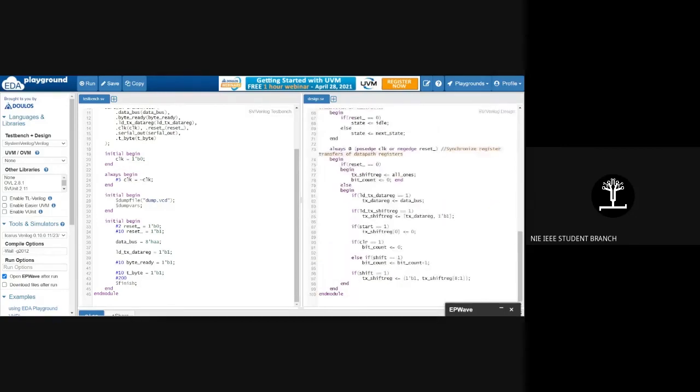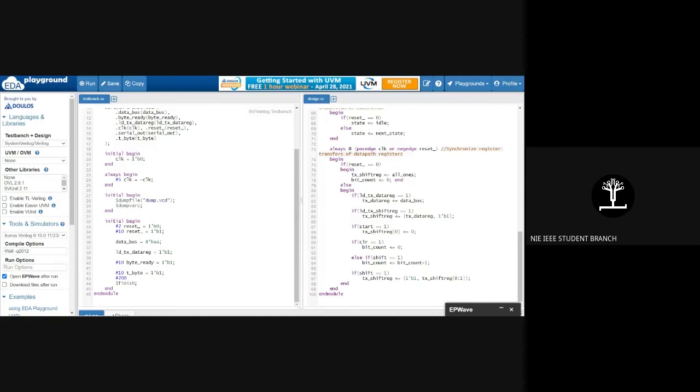That's how it is. Now comes some of the most important parts. Now I have to synchronize the register transfers, from the data register to the shift register and shifting right, and such kind of operations is what I'm supposed to look after. Now I've taken care of the transitions, that is of the controller. I've taken care of all the states, when what should happen at what states. Now I have to take care of the transfers. We are going in a certain order so that things go well. So again, if reset is pulled low, what should happen to the registers? Not what should happen to the state, or to other things. We just care about registers now, because register transfer is what we are thinking of now.